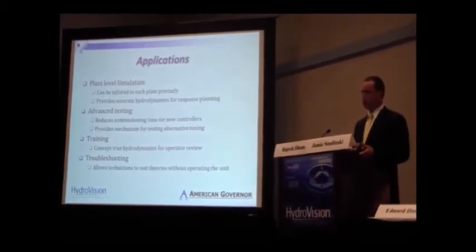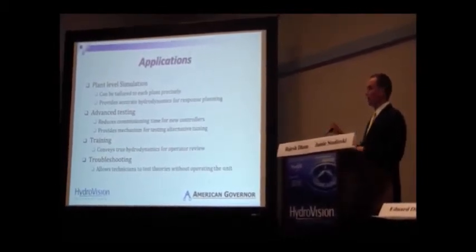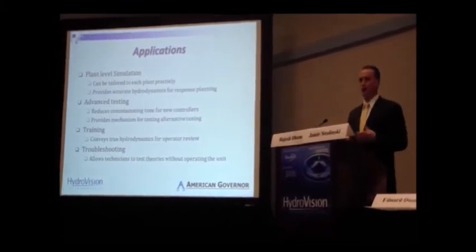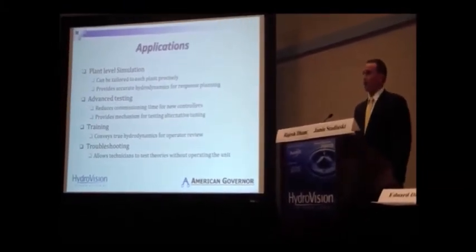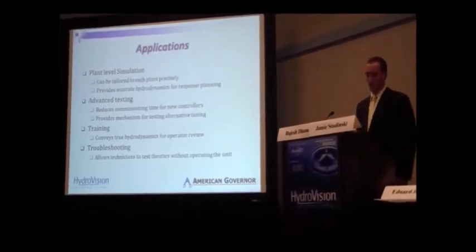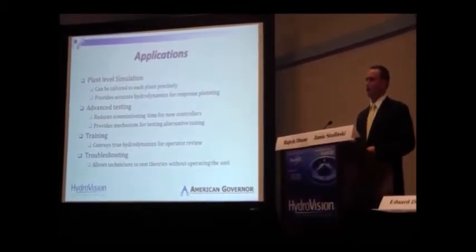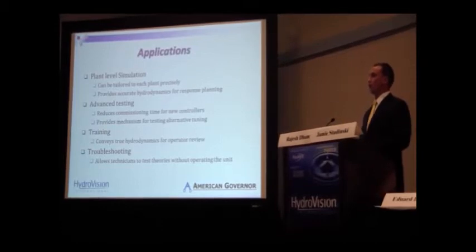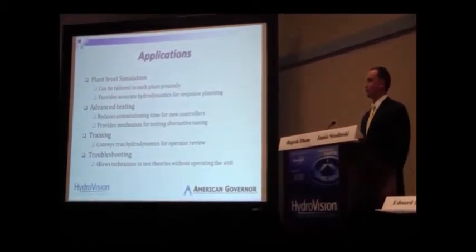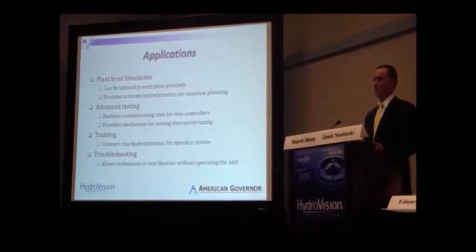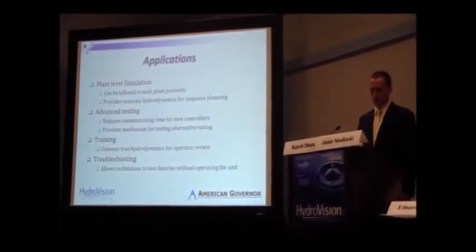So the actual concerns over grid stability can go beyond the unit view itself. If you're starting to consider how those would affect different plants, or how that would affect the grid as a whole, you can actually virtually try to come up with a new scheme. At Grand Coulee, for instance, we use a lead-lag controller, not a PID. There are other methods of control algorithms that could be tested in any given scenario, so it gives you some advanced planning capabilities.